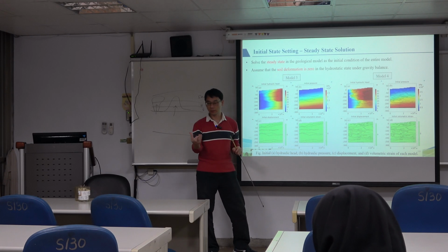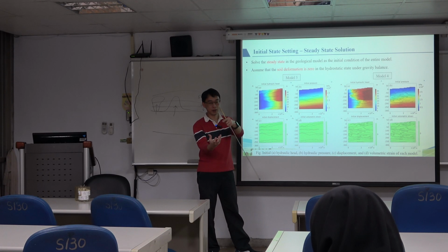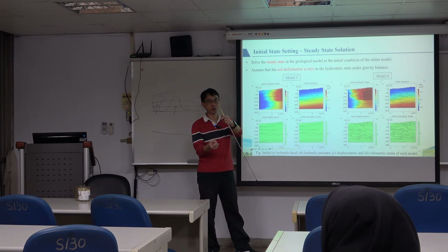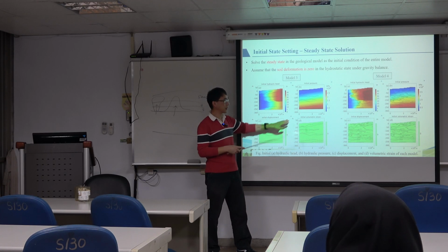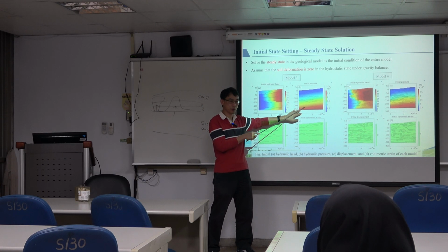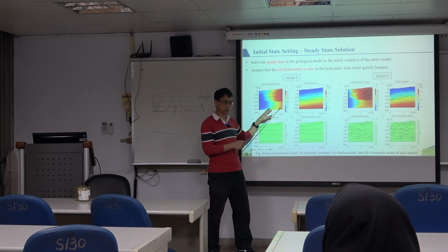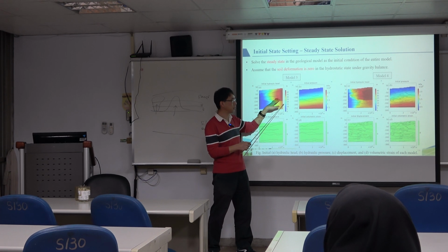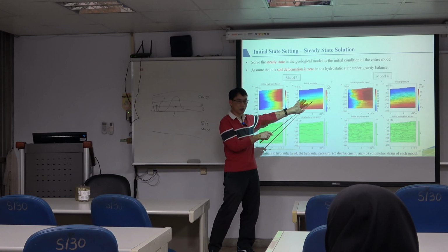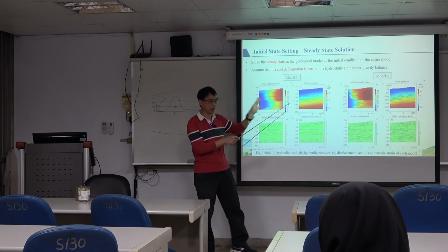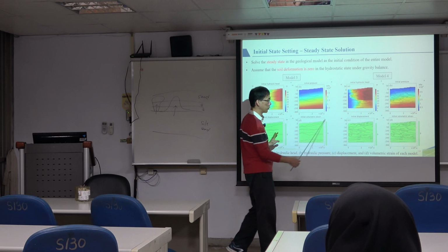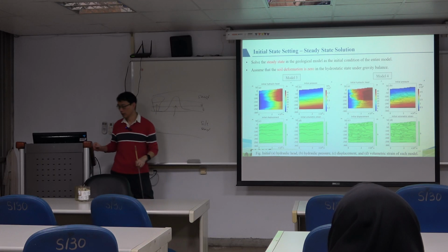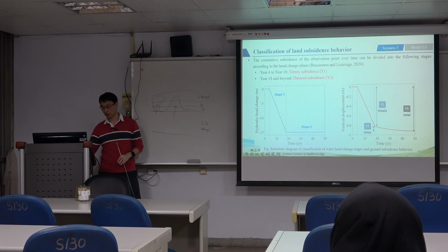Imagine a bottle of water: the bottom of the bottle has high pressure, but the water inside does not flow, right? So it becomes a relatively steady state condition. So remember that water pressure is not the driving force for your water flow, and head is the driving force. And we mentioned that head includes the pressure head and elevation head. Okay, I hope you can remember that. The displacement we set up initially to be 0, so we do not spend much time here. We just take a look at how it affected the result.